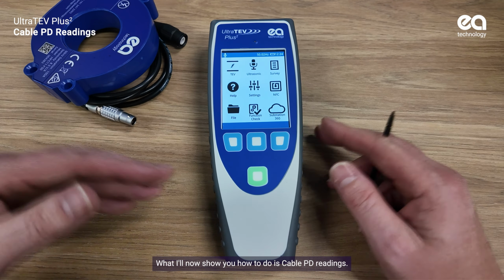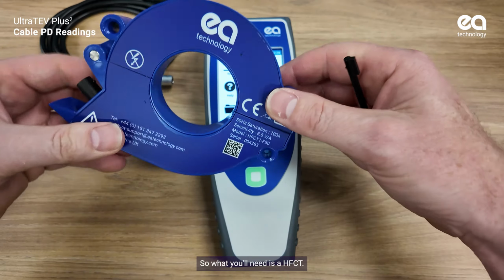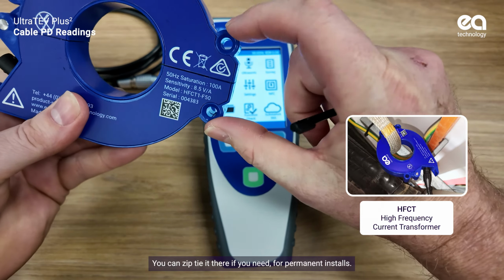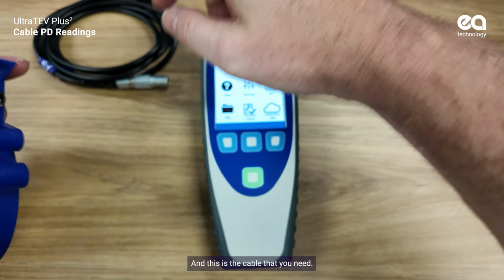What I'll now show you how to do is cable PD readings. So what you'll need is a HFCT. This is a HFCT, a high frequency current transformer. It's magnetic. You can zip tie it there if you need for permanent installs. And this is the cable that you need.